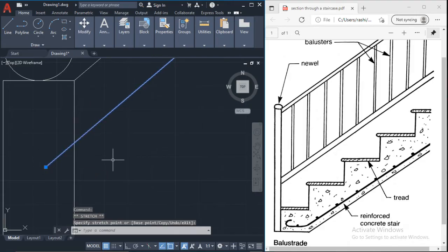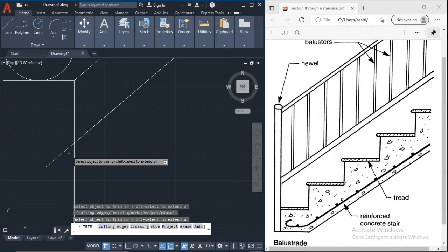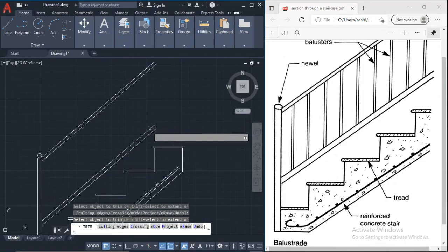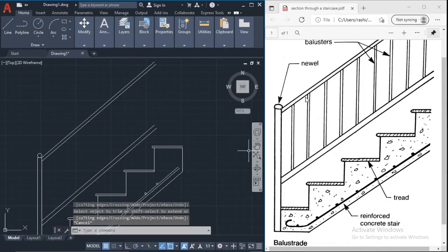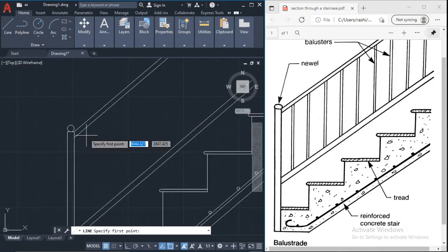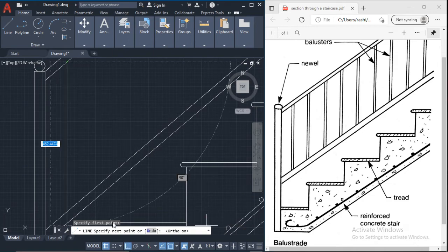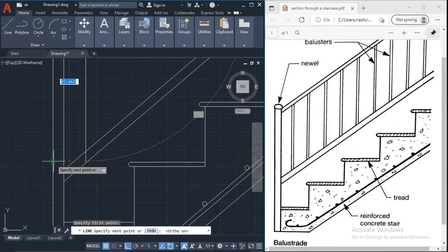But in this case, we're not drawing it from a floor plan, we're just drawing it from an image without measurements. All right, so we have those. So now we need our balusters. For those, let's say that our balusters are about 10 millimeters. So we start here. Let's make them about 10 millimeters, 100 millimeters apart.